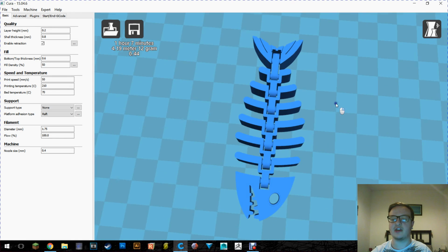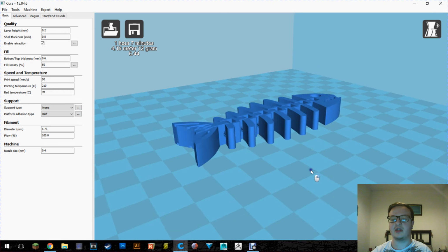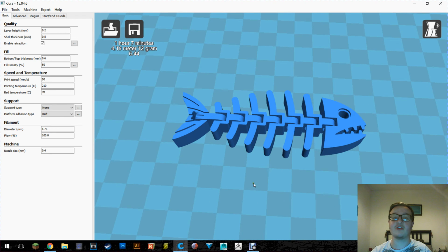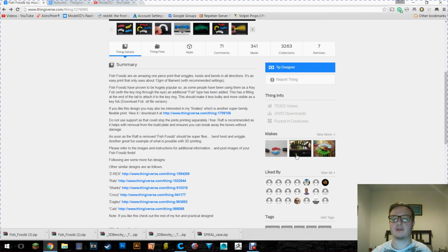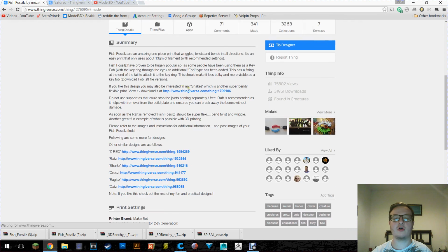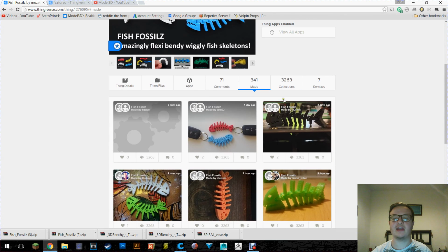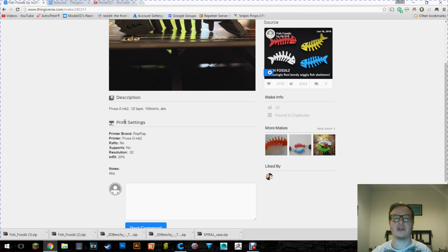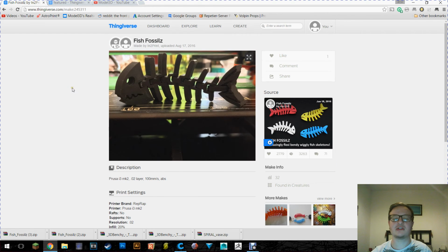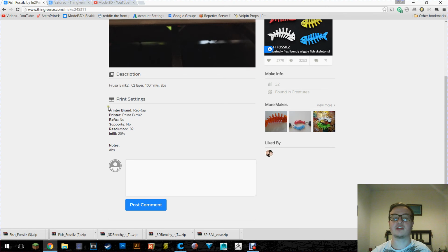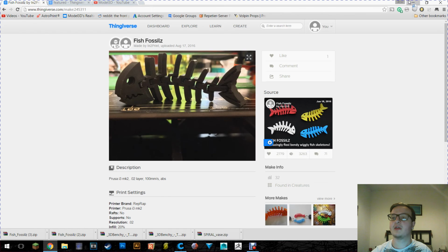We know we don't need any supports or anything like that because the website told us. If the website doesn't tell you what you need, it might be worth looking through some of the already made ones. So if you look down by here, you've got makes. If you click view more, it'll be all the ones that people have made, and a lot of the time you can click on them and it'll tell you their personal print settings. So if the main one doesn't have the print settings that you need, a lot of the time the makes will. But as you get more aware of this and as you do a lot more printing, you'll learn to know your own 3D printer settings and when to use infill, all that kind of stuff. So you probably won't need these tips in a couple of months anyway. But yeah, that's all well and good.